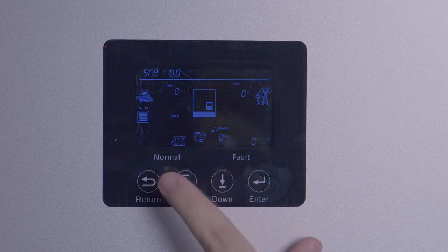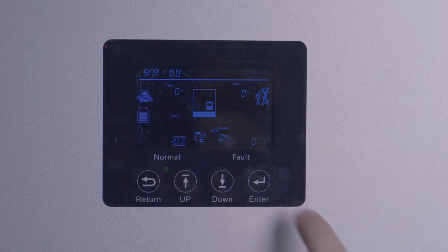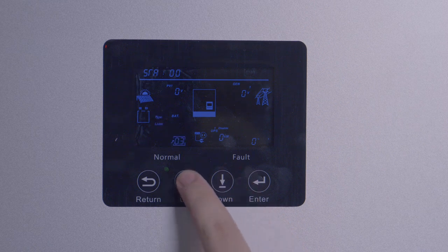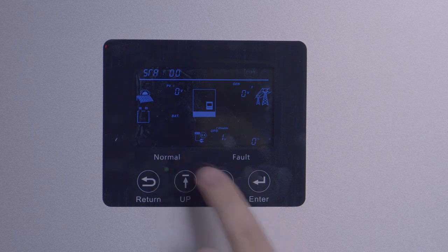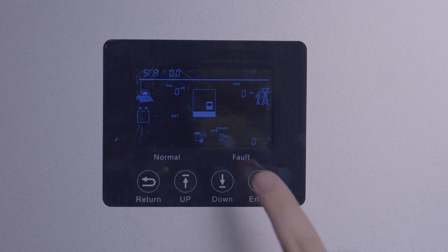Setting 3, battery type, is very important. This can be set to lead acid, which doubles as open loop lithium, Li-ion, which is the closed loop lithium setting, and no batteries, which is very niche and not recommended for normal operation.